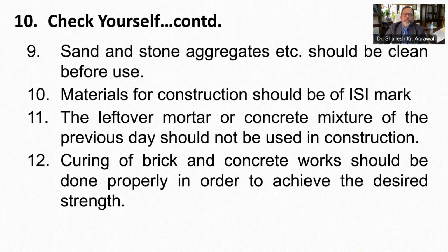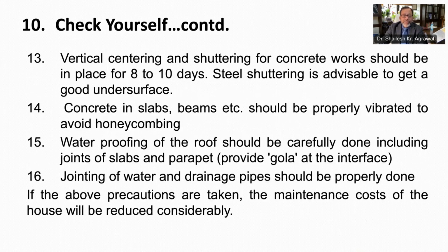The leftover mortar or concrete mixture of the previous day should not be used in the construction. Curing of brick and concrete work is very important and should be done properly in order to achieve the desired strength. Vertical centering and shuttering of concrete works should be in place for 8 to 10 days. Steel shuttering is always advisable to get a good undersurface. Concrete in slabs and beams should be properly vibrated to avoid honeycombing.